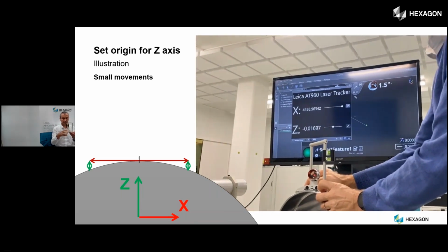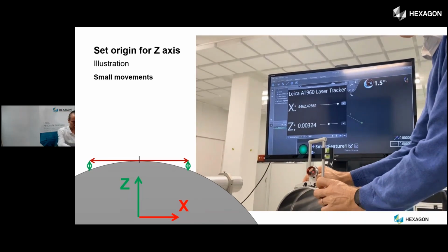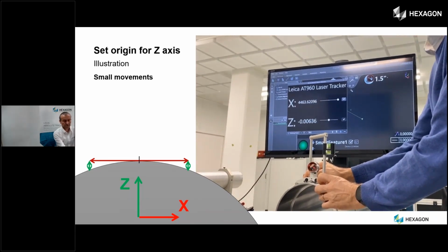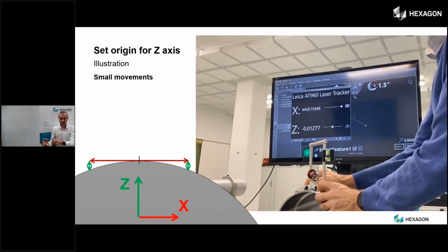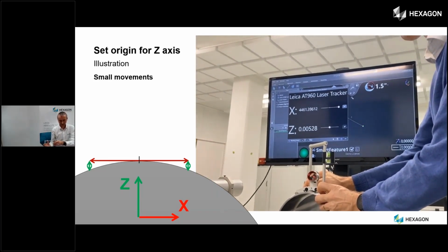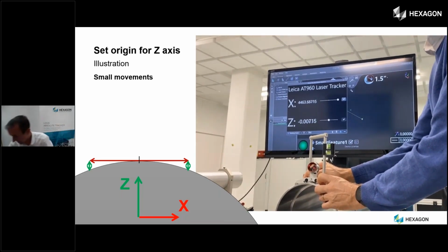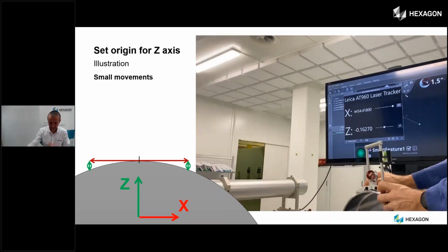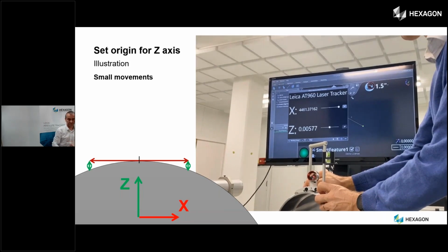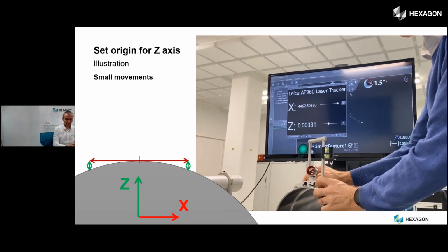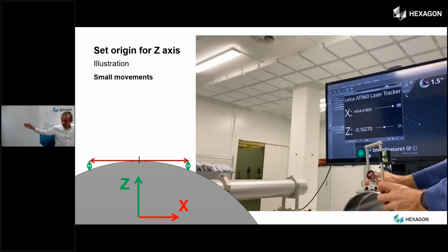So you will adjust this with the spirit on the front side approximately, move it to the adjustable end, adjust the height, and then you go to the right side and do the same thing to adjust the X-axis, to set X-axis first to 0, and then go to the adjustable end to adjust the X. And if you have very much adjusted the X, maybe you need to go back and adjust the set again a little bit. So this is adjusting a roller perpendicular in a way to the reference line, which was given